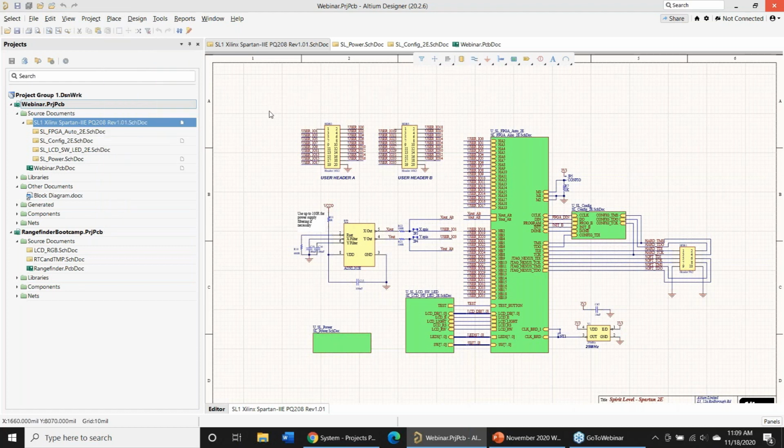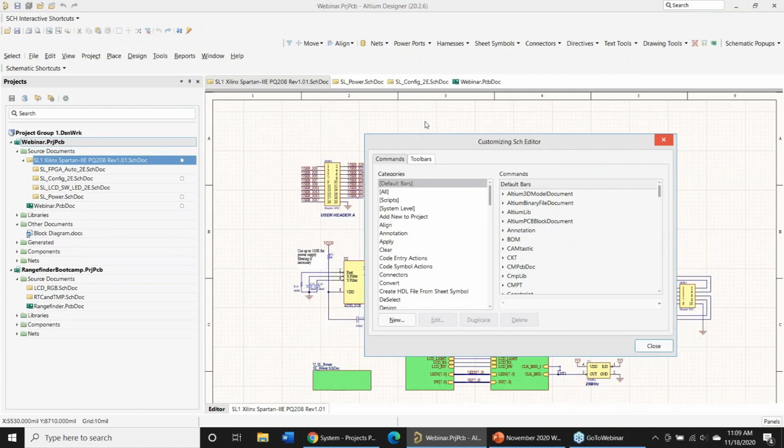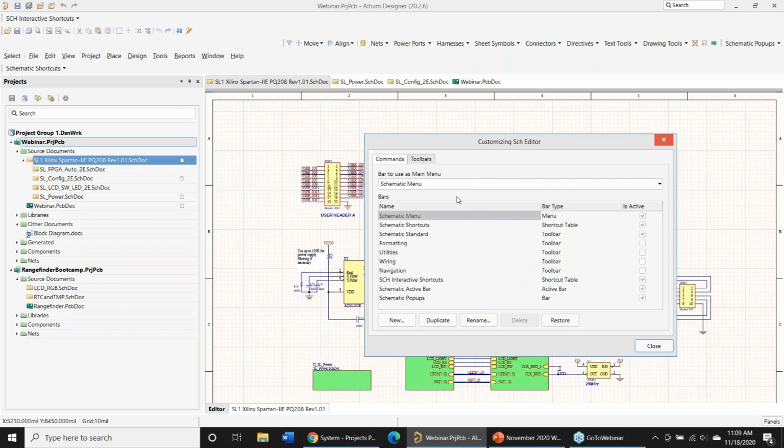But if you do something very often, and especially during navigation, if I'm going to look for things, I want to be able to set things up. So setting up your toolbar is really nice in there. You can set up different toolbars here, but you can also customize your toolbar. Altium does something a little bit different than it normally does when you have a dialog open. Normally, when you have a dialog open, there is nothing else you can do in Altium. Once you come over here, it'll ding at you every time you come out. But when you're in this customize schematic editor toolbars, you can actually start editing your toolbars over here.